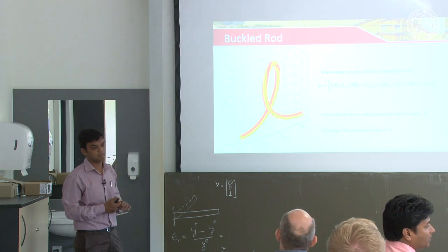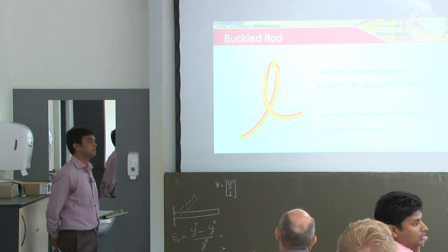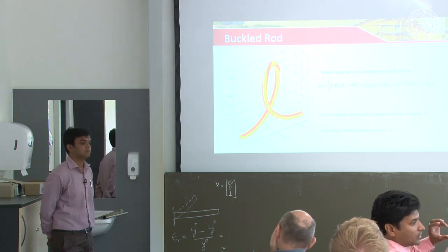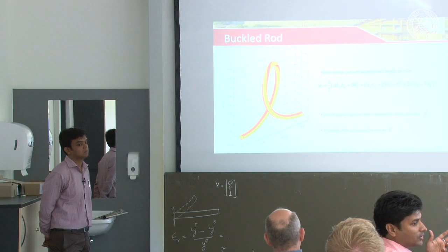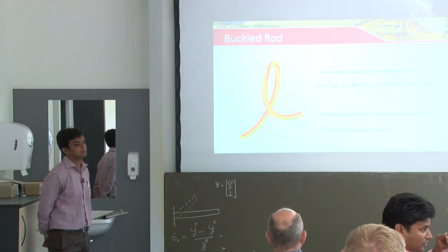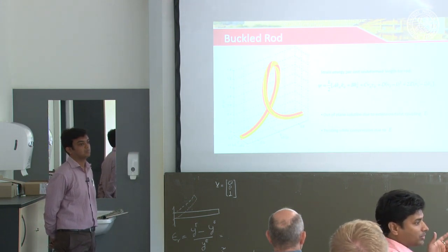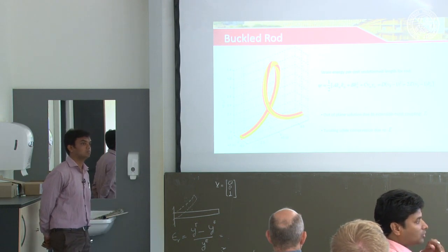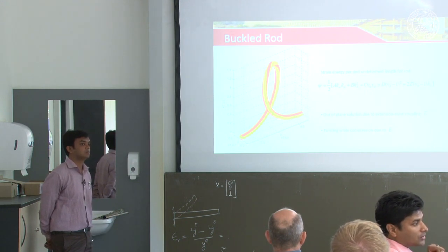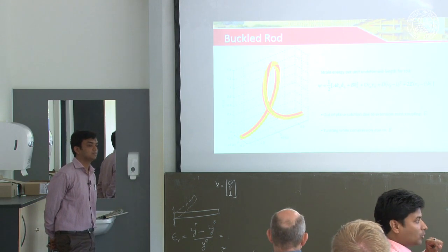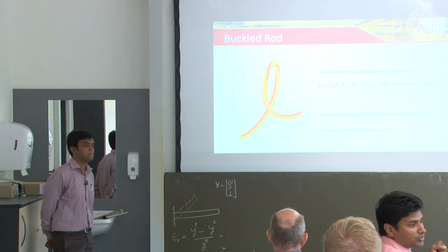There are many applications also in nature. For example, you must have seen the picture of DNA. It has that helix-like thing. So if you want to think of it as a continuum beam and want to incorporate the helicity of these strands, then you have to think of it as a pre-twisted beam. A beam which is already twisted, but there is no moment in it. So it has intrinsic twist in it. Which means although the beam has got twist in it, there is no twisting moment in it. So it is naturally having that twist.